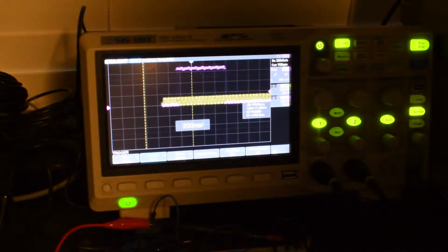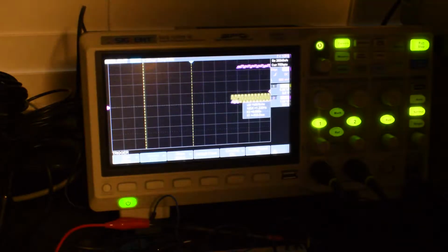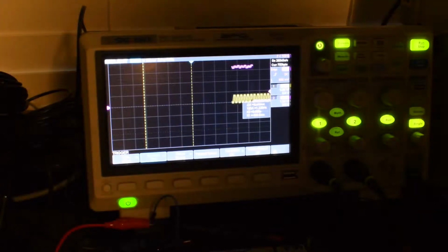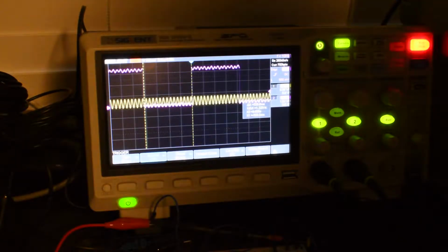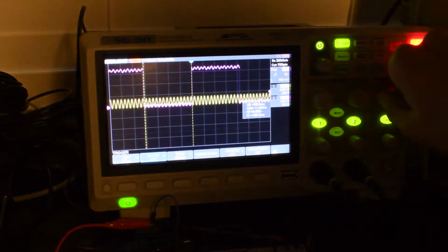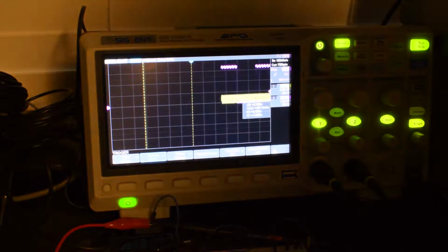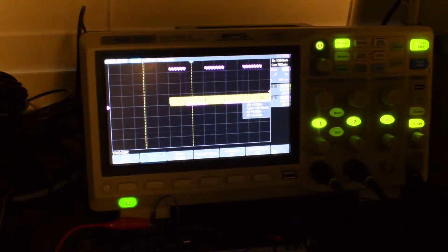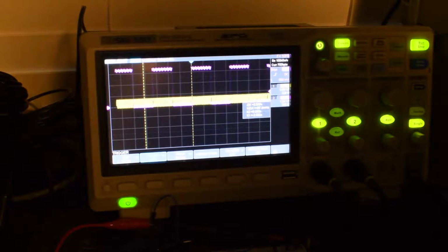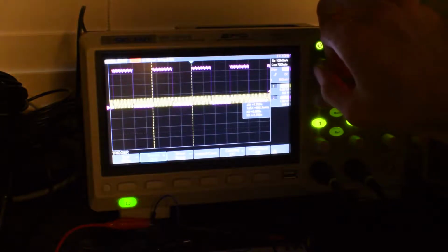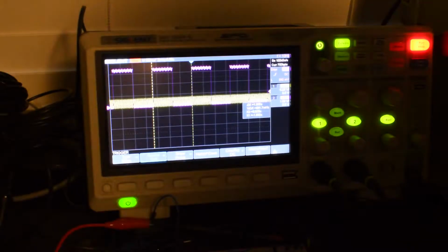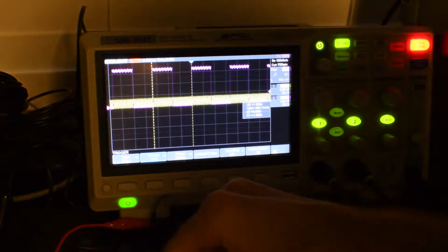And this is what it looks like in between the second and third counter. So you see now it takes much longer to go through one complete cycle. So when I put it in that roll mode, it's scrolling across in real time, so you can see how slow those pulses are now. So right now, one complete cycle of this square wave is 1.69 seconds. And so the one we're actually going to read